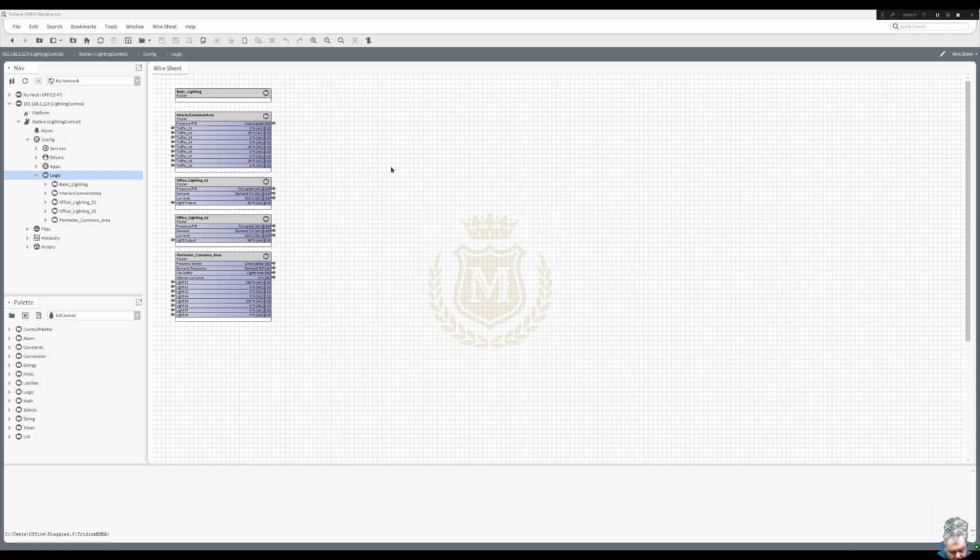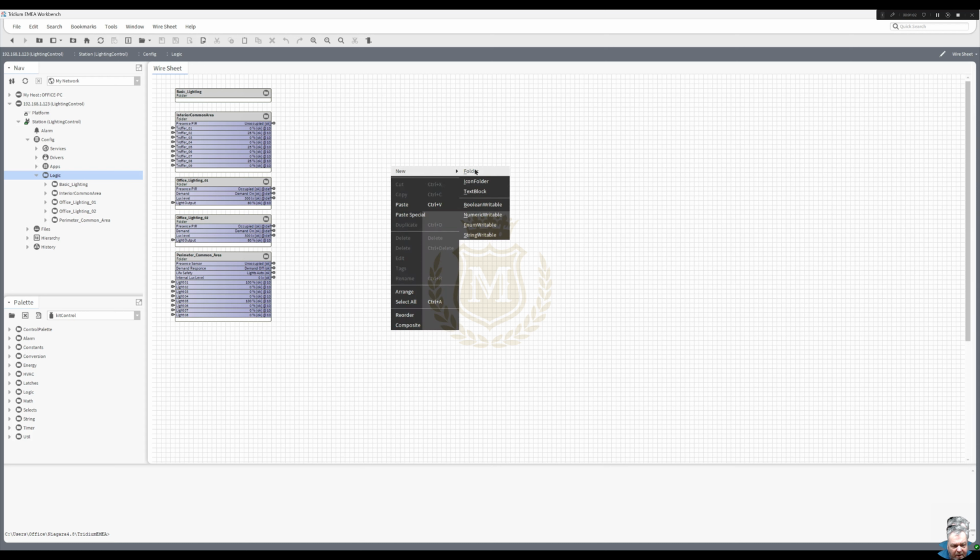Now this block, we will composite the blocks to the outside. So this one folder will go into your logic. You just drag it and drop it into your logic. So if you've got a 2-pump routine and you want to latch the fault, you would just put the points into this composite block, ready for you to duplicate it again for the other pump. And it doesn't have to be pumps, it can be anything that you want to latch. Let's start and you get an idea what I'm talking about.